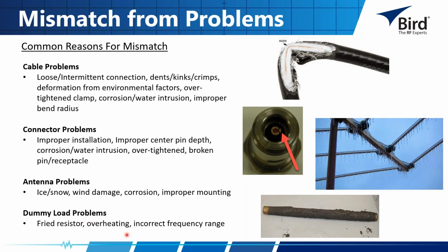Overheating can also result in that. If you're performing a measurement in a place that maybe has a covering or something like that, that's not letting the unit radiate the heat away properly, or something that might just have a high ambient temperature. And actually, one that I've seen that's pretty interesting around the overheating side is I've seen guys that attach the sensor directly to the load, and when they're running at a higher power, they're actually getting a large thermal transfer from the load over to the sensor.